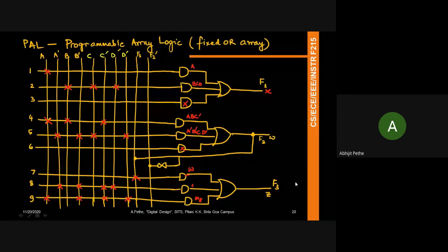And so when I give you the 3 functions, make sure you get all the expressions down to a minimum of 3 SOP. You can't implement in this PAL a function which is written in a form which has more than 3 product terms. So ensure that all the functions have at most 3 product terms, and then you can do this. In this case, sharing of functions is not specifically that important, but if you can reuse a particular function, then try and think about that.